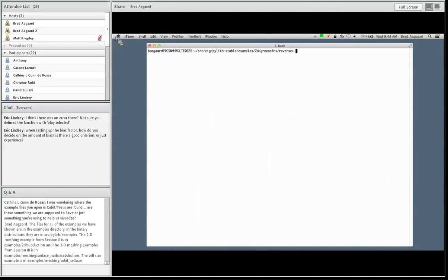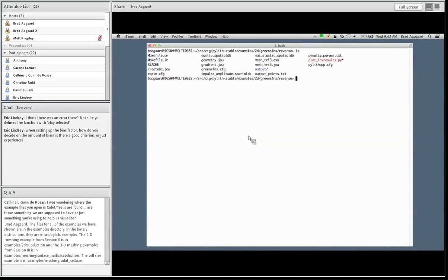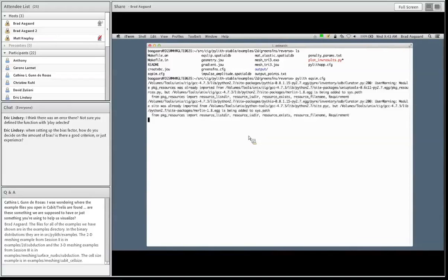And so it ran. Here's all the log information from PETSc. Did our solution converge? It did, taking 98 iterations. That's additive Schwarz. Matt will talk in the next session about being able to improve that quite a bit using alternative preconditioners.